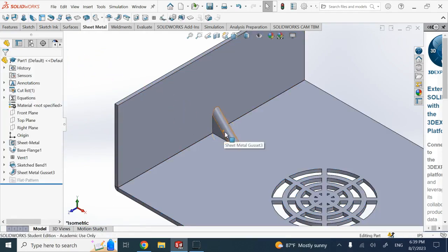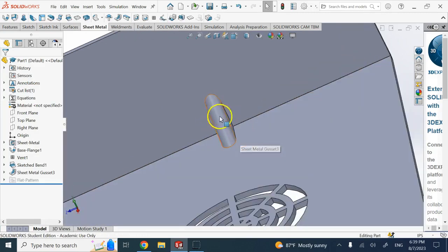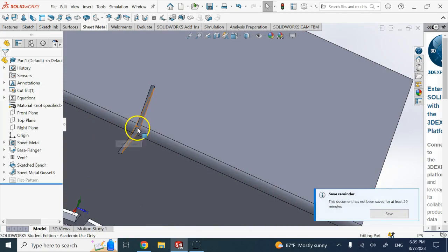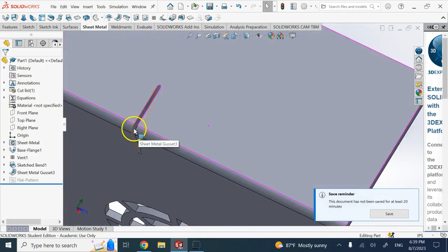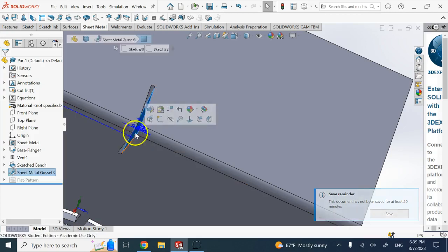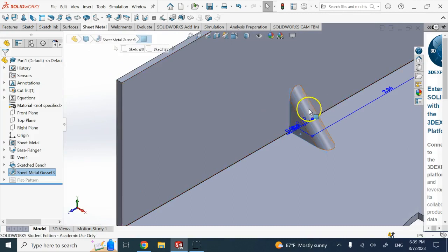Now pay attention that gusset is not an extra piece of sheet metal that you brought and basically added. If you look underneath it, you see here this gap, okay? So it's basically like you have some tool here and then you push the sheet metal outward, so you got the gusset, okay?